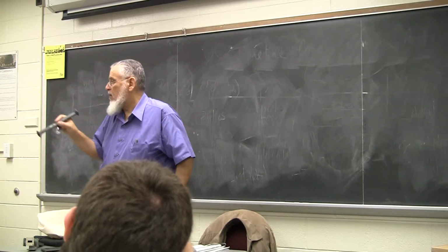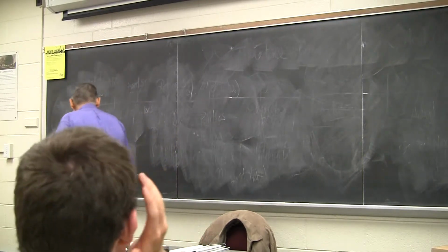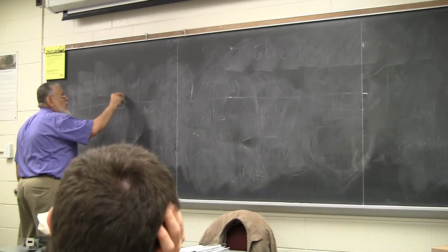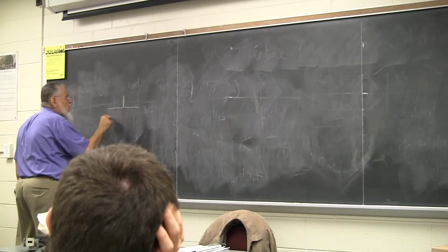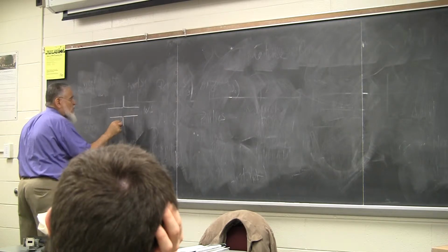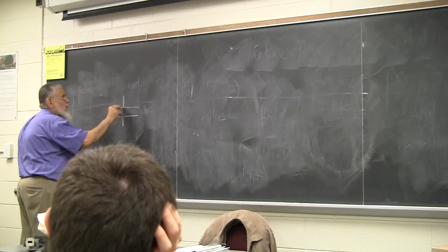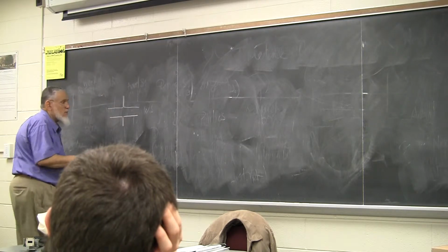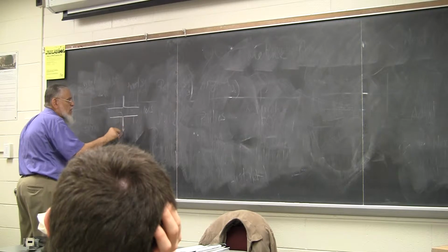electromagnetic, right? The inner one basically, if you are putting the waveguide together like that, and you rely on the metal touching the metal here and causing a short, you stand a chance of irregularities in the surface and energy leakage out there.